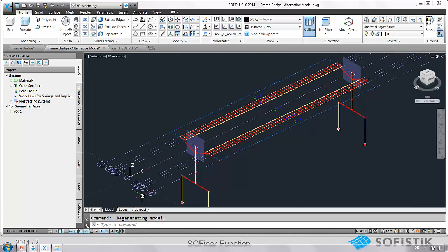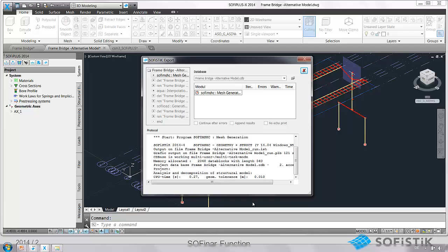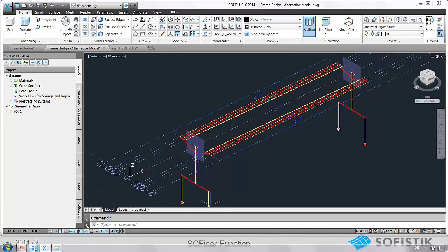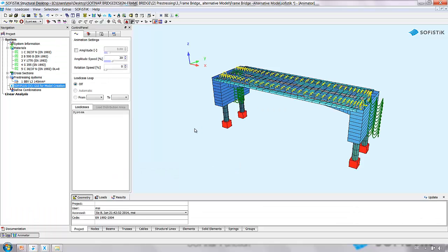So it's a bit easier now, but we still have the same aim: only the girders should bear the loads in longitudinal direction, and that's why we have to define orthotropic behavior for our shell elements. In this example we're not going to do that in the structural area properties. We will do it in the program ASI. For that we have to make an export of our system.